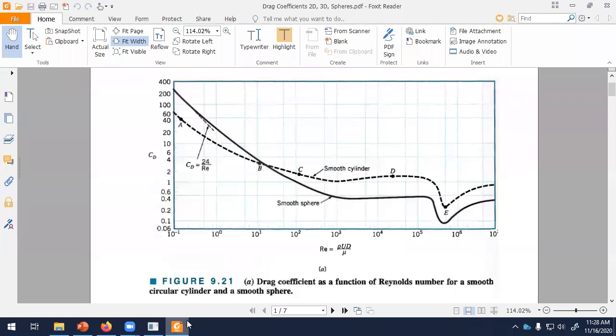Well, it's not letting me write on this, so let's try annotation. There it is, thank you. So in this case, what we're looking at is this region. And in that region, again, with an increase of the Reynolds number, you get this precipitous drop in the drag coefficient. That's what the trucks are trying to do when they add the spoilers.